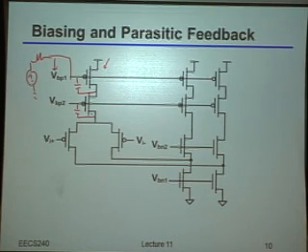Of course, I'm also going to have a CGD in that transistor there. And of course, I'm going to have CGD in this device, that device, this device, this device, and so on and so forth. Okay? So now let's just do a simple thought experiment. Let's say some cosmic particle comes in and hits your circuit, and just so happens to make this bias voltage go higher than it used to be. So what I want to do is walk through which direction every single node in the circuit gets moved due to that, to see what kind of feedback we're going to end up with.